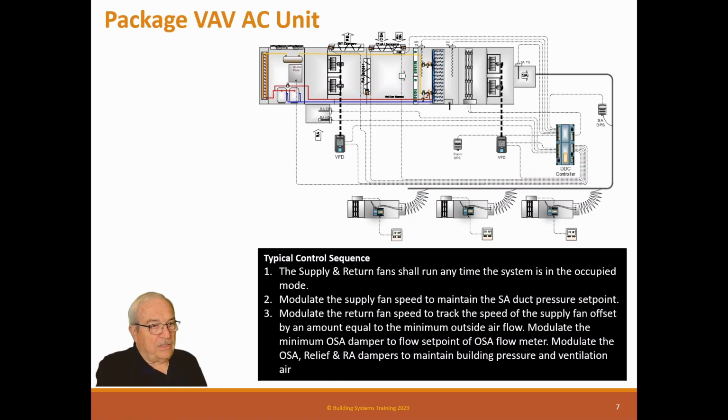Now you can't physically stop it, but you say, okay, now when the unit's off, this is 100% closed. When the unit's on, at this speed, we want it to open this percentage. When the fan speeds up, we want this percentage. And we try to guess what that is. We never get it quite right. It's impossible to get perfect. But in this situation now, these are controlled totally separately, and we can't do those.